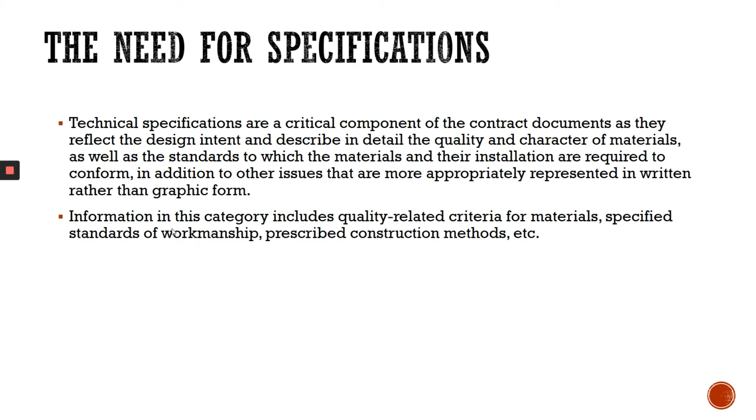Now let's look at the needs for specifications. Specifications are a critical component of the contract documents. The client wants something, but you give the client something else. And then you will have disputes with the client and also the contractors. So it's very critical. Specifications describe the characters of materials, as well as the standards to which the materials and their installation are required to conform, in addition to other issues that are presented in written rather than graphic form.